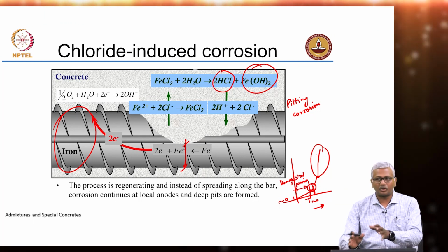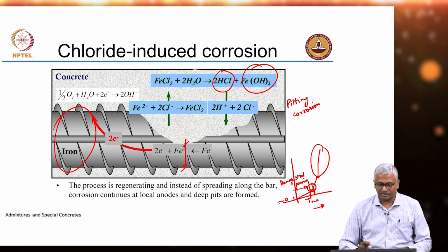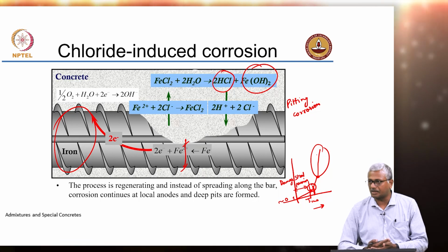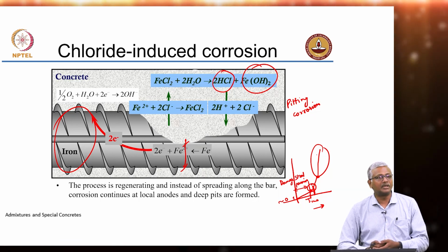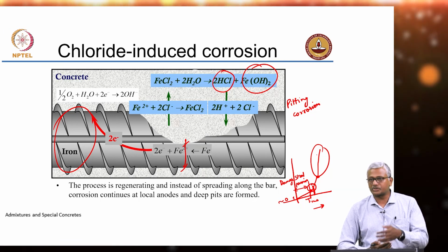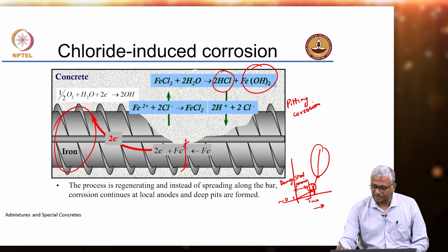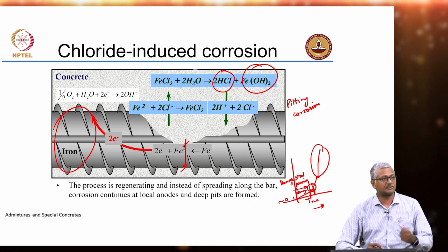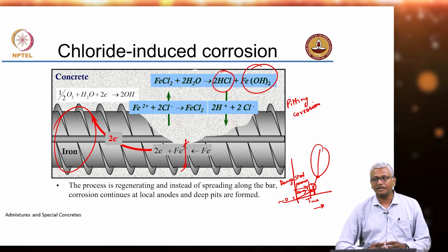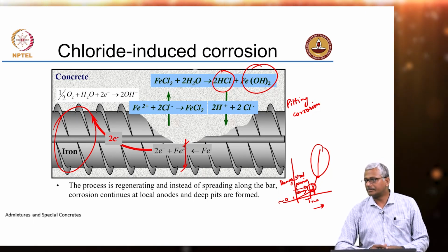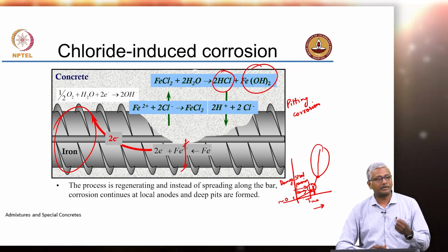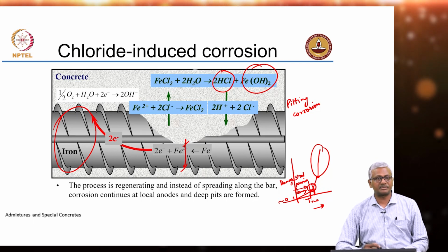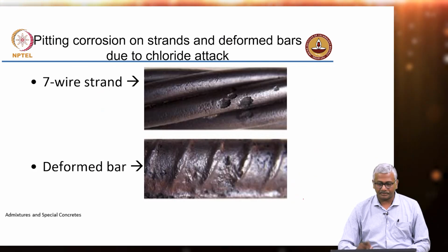So, again, I am not talking about modeling in this chapter, but what I will essentially talk about is where we can start looking at solutions to increase the service life. Mostly we will want to work in this time for depassivation of the steel. That is where we want to really focus our recovery or our repair, our strategies for increasing corrosion resistance of the reinforced concrete.